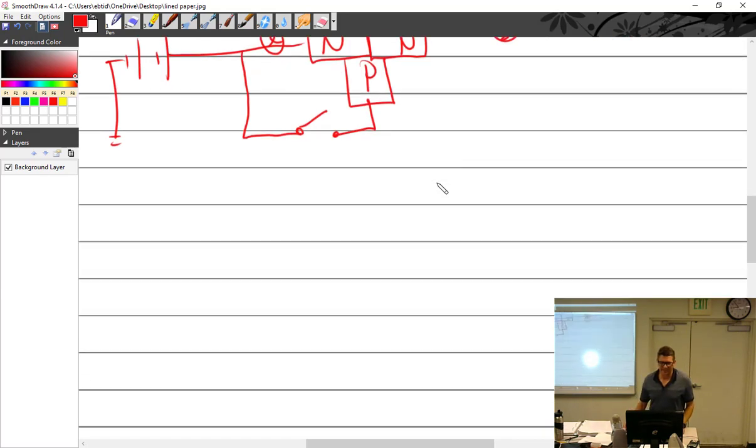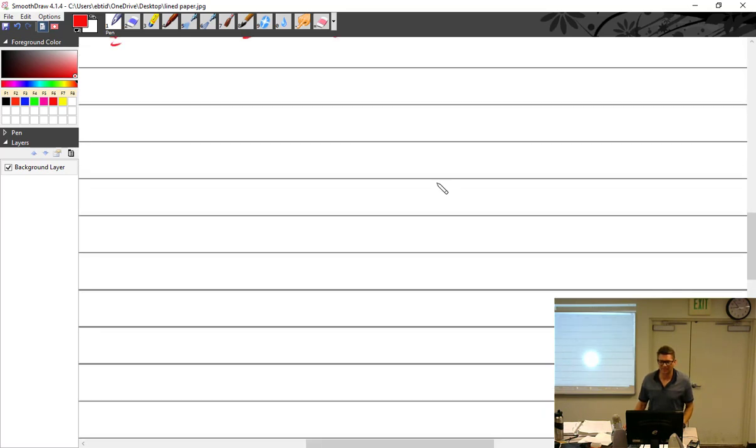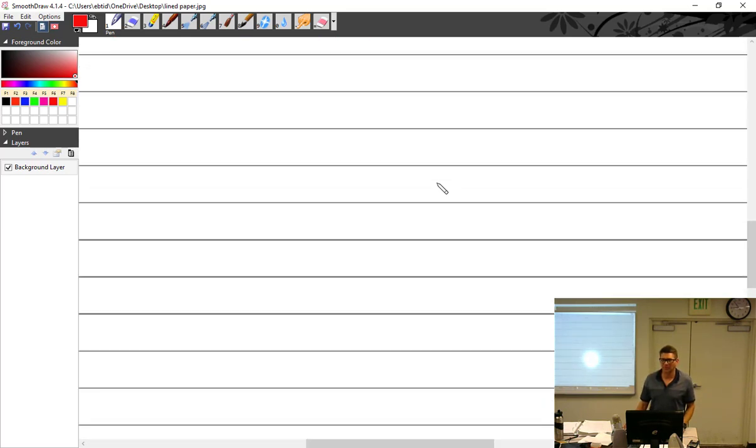All right. Kevin, how do you figure out polarity of a transistor component when you have one in your hand? Oh, man, I should have written that down on here. I can't believe I don't have that on here. Well, one thing you can do is use a voltmeter and figure out which way is forward bias and which way is reverse. The other way is that they're always marked.